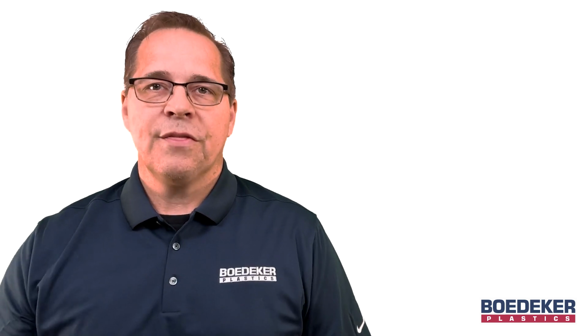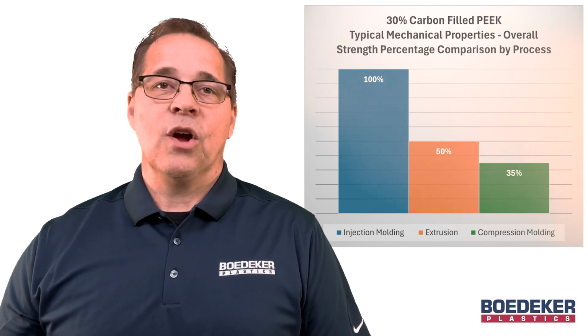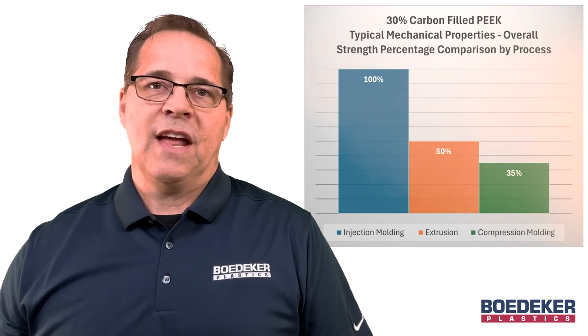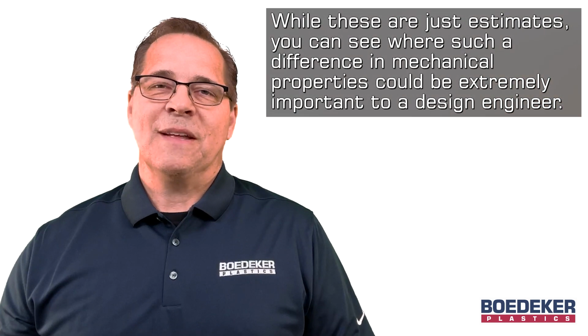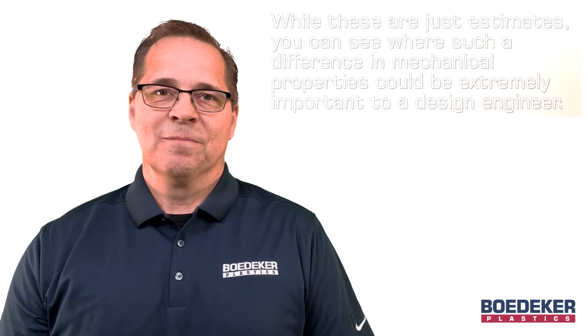A typical rule of thumb for fiber-filled materials like a 30% carbon-filled PEEK is that injection molding properties can be over 50% above extrusion properties, and the extrusion properties will be another 15% above compression molded properties. While these are just estimates, you can see where such a difference in mechanical properties could be extremely important to a design engineer.